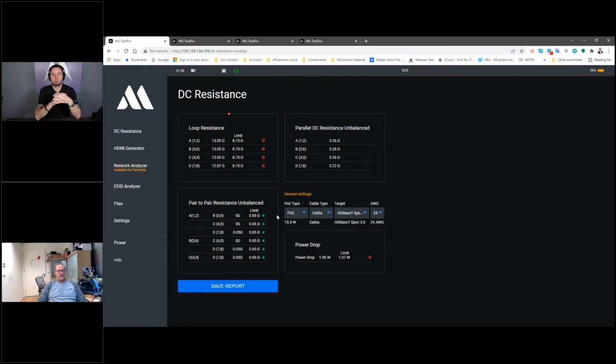Think about it. You need to drive 24 volts or 12 volts or 5 volts from one side to the other. If the resistance is high, the drop on the category cable for long distances will be high. It means that the remote side will get from you very low power. It will get a low voltage on the remote side. This low voltage will actually keep the remote unit from working properly. So it is important. Same thing goes for the propagation. When you try to drive the signal through the cable, you will get fails.